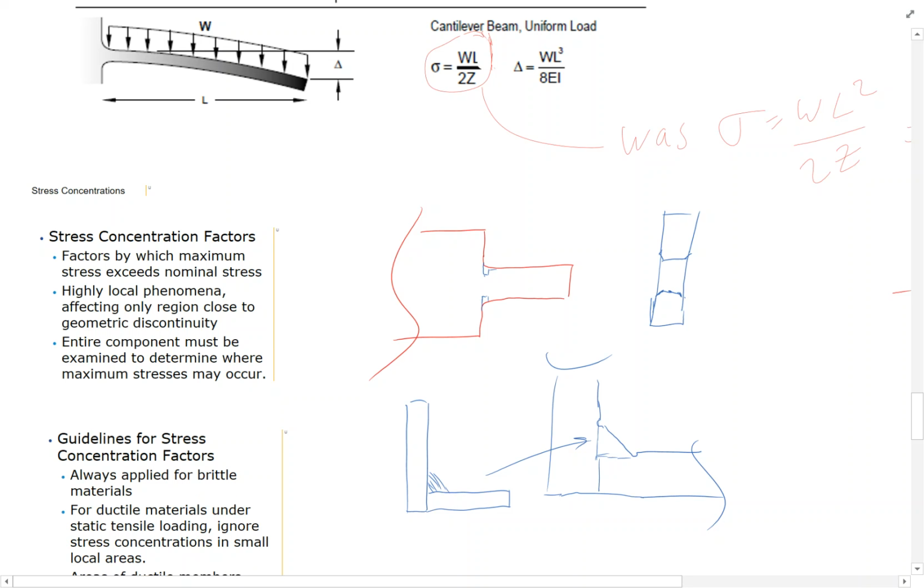So manufacturing can end up causing a lot of fatigue failures, and that's the example I'm showing here too. If I'm doing machining and I'm going to turn this little portion of a shaft onto the main body of this thing, and the print calls out a radius here, is that radius easy for me to put on? If I'm on a CNC lathe, it's easy. I just program the radius.